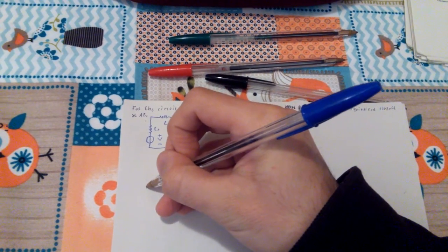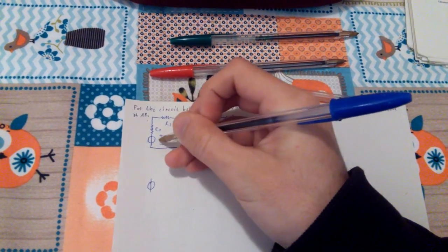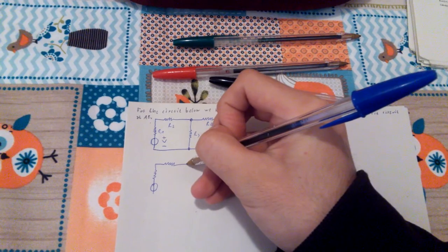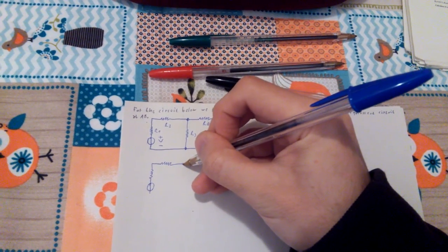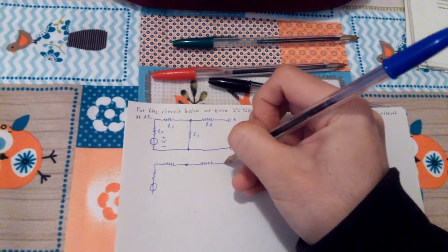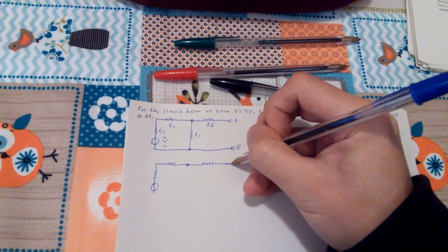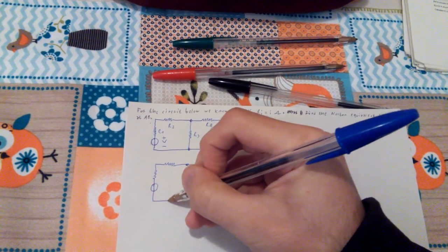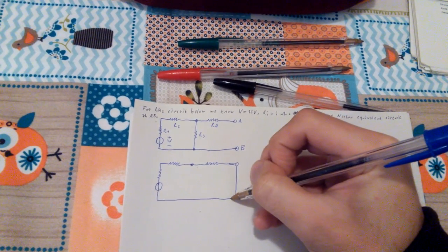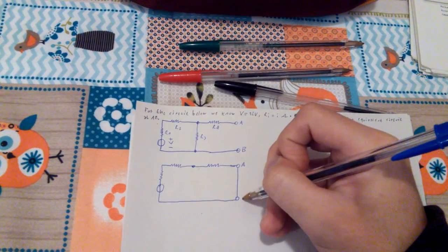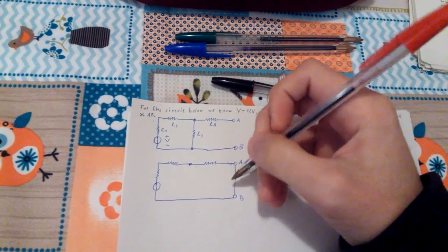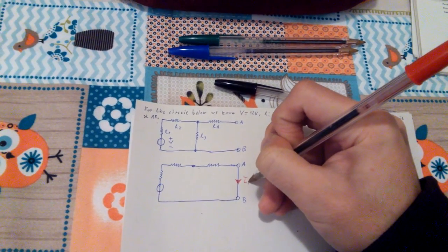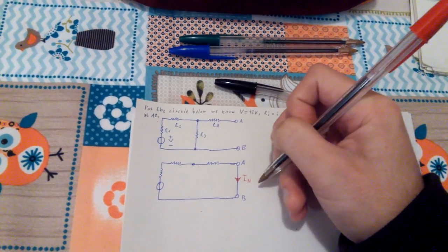I basically mean this. I'm still going to have my voltage generator here, my resistance here, another resistance here. This is a node, and then another resistance here, and then I'm going to have A. But note here between A and B, I'm going to have just a wire. This is going to be my point B. So this is still A, this is still B, but now what I'm looking for is this current flowing through here, which I'm going to call I of N, or I of Norton.